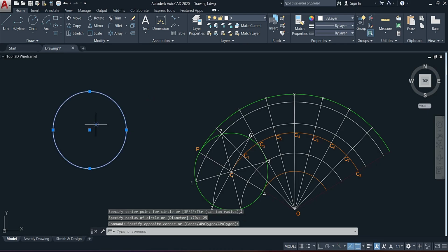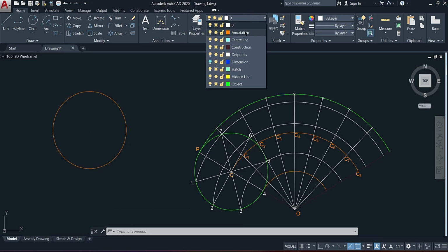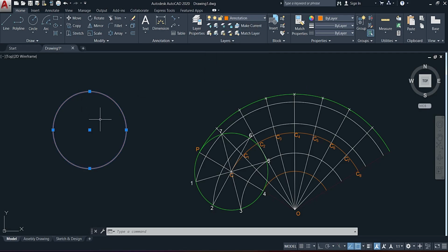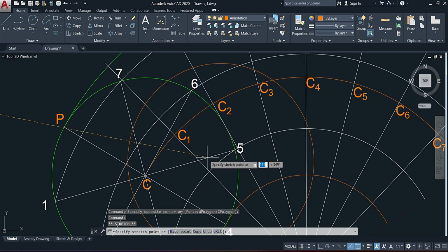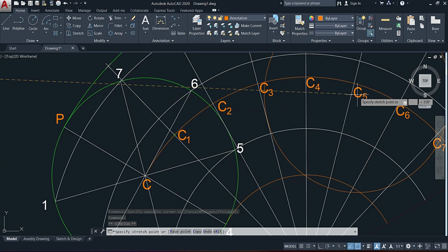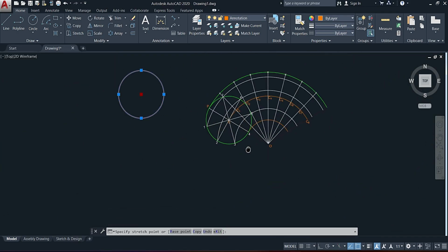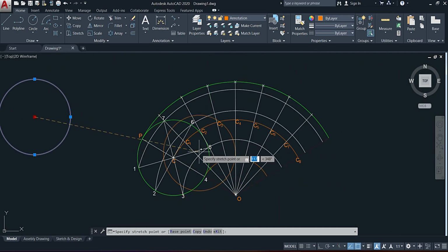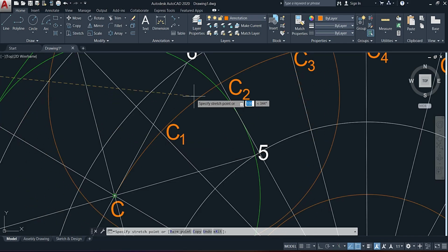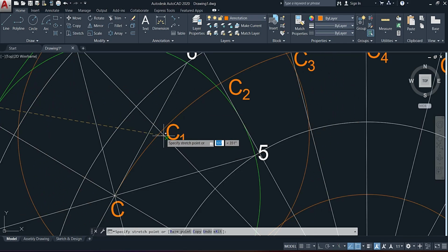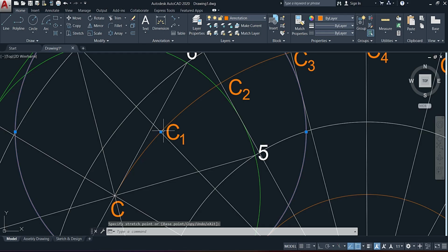Now this circle here, let me switch the color to something else. You know what, let me use this orange color here. This center is going to be moved through all of them, C1, C2, C3, C4, similar to the epicycloid. Let me kick things off at C1, wherever the orange line intersects with the dividing line, so that's right there.